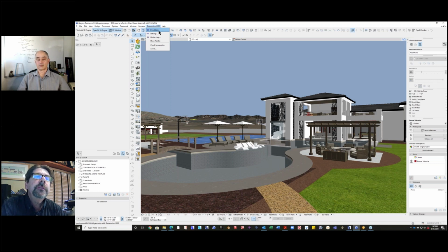And then when you continue editing your ArchiCAD file, you'll redo that, and it will just suck the new stuff in from ArchiCAD into your Twinmotion. So all those trees that you placed are still there. If you change the materials, for example, if Twinmotion has a better stucco, you can edit that, and all those relationships will still remain as long as you name the material the same, which you would. So it's fairly fluid.